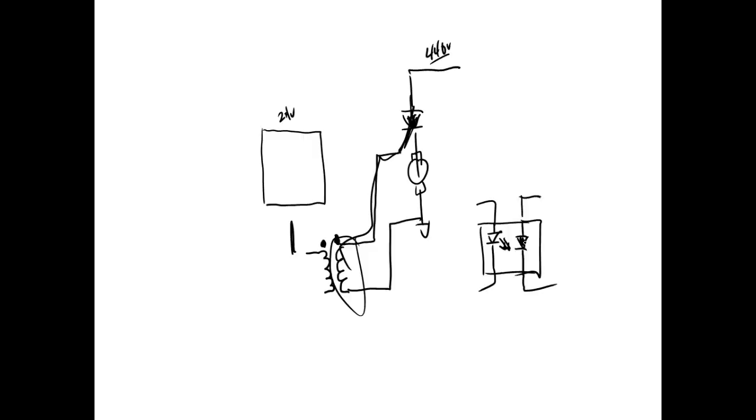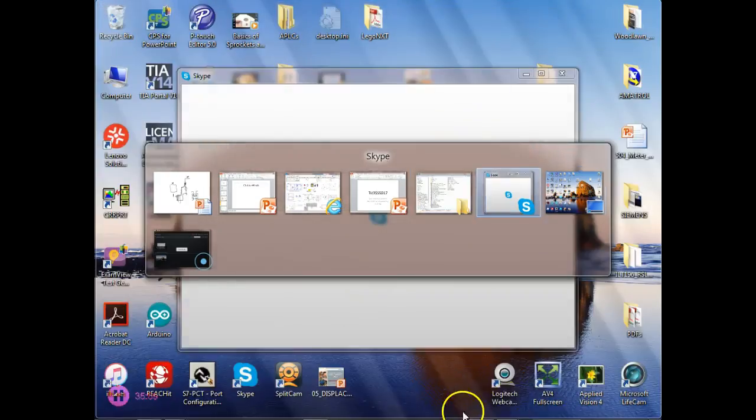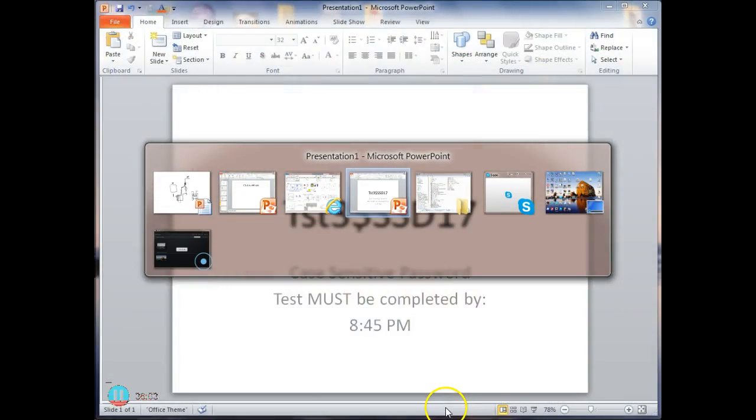So you'll see pulse transformers, and what you'll see is these pulse transformers will be mounted out on the package with the SCR. And then they run two little wires back to your PLC, back to your control program. There'll be one red and one white wire. The red wire will be your gate. And so your pulse transformer is even out there with your SCR. But this is the circuit. The other circuit is the one I'm working. So where's my power?